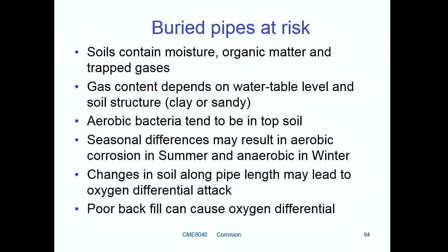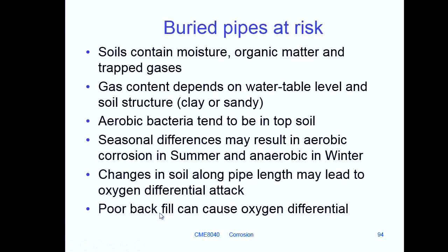Again, you don't particularly need the details. These are two images. One just illustrates that if you've got a length of pipe, the soil composition can well change as you go along the length, and when you get an interface between, say, a sandy soil that's going to be oxygen rich and a clay soil that is going to be low in oxygen, then you've got an oxygen differential, then you can get corrosion. So you've got to watch as you move along the length of the pipe that you're going into different soil structures.